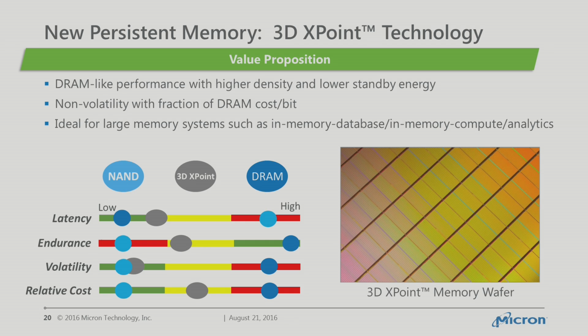With as good as NAND is, and it's a wonderful memory compared to a hard disk drive, any spinning media, it's way, way faster than that. Yet there are things NAND can't do very well because you have these quality of service issues if you're in a high performance kind of system. And so the 3D crosspoint fills that in. And there was a third point,